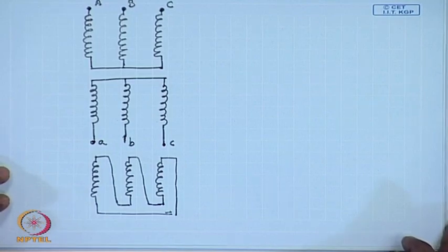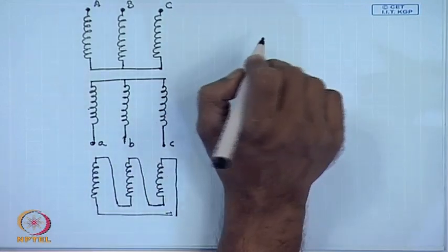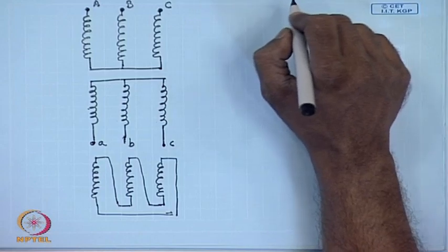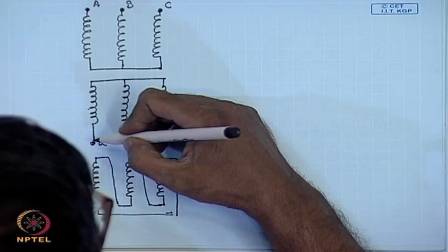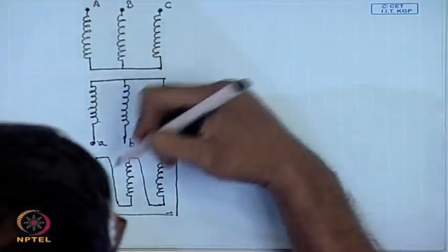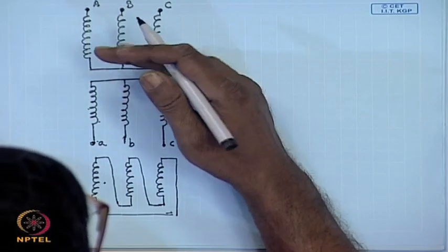Hence, by the similar argument, the 3 winding transformer can also be analyzed per phase basis, and on steady state, if we consider a single phase of all the 3 windings, we can write the applied voltages and the currents as follows by referring all the voltages to the high voltage side.